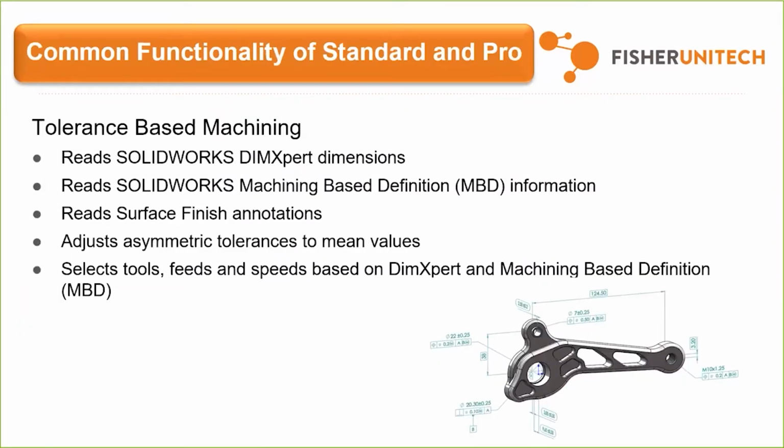You also get what's called tolerance-based machining. Basically, tolerance-based machining leverages your DimXpert dimensions and your PMI data to select the correct machining strategies. So it's worth noting here that SOLIDWORKS CAM is currently the only CAM solution out there that can utilize PDM data to program.